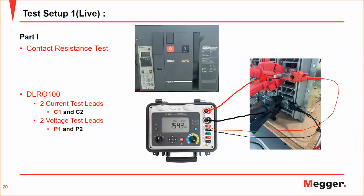Okay, the next question is, can I perform contact resistance tests without isolating the breaker? Usually it's not something you can do, but are you talking about a medium voltage or high voltage circuit breaker? In medium voltage, you have to isolate the circuit breaker. It's usually very easy. You just rack it out of the cabinet. And for high voltage, you cannot really do that. You have to separate the breaker and do this test.